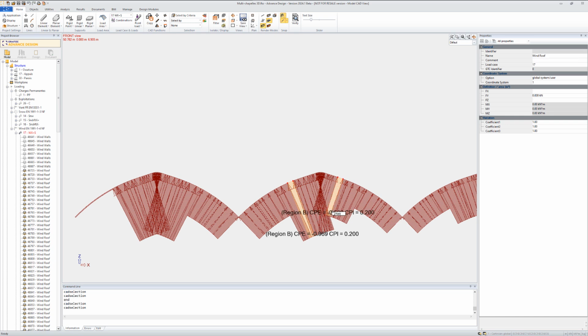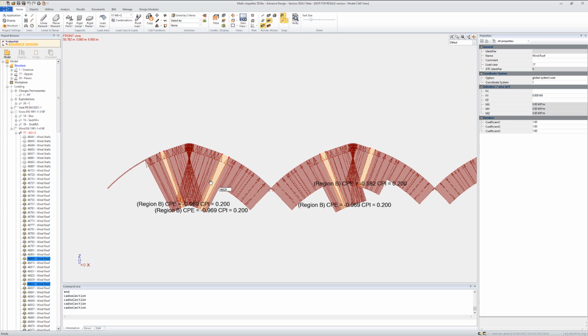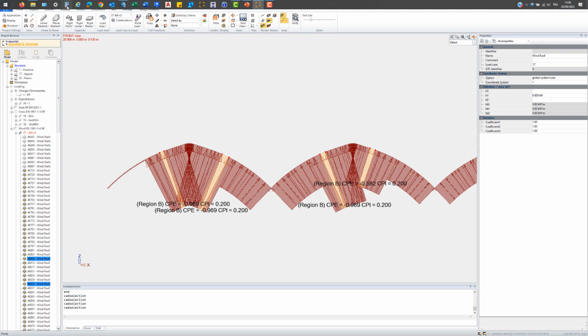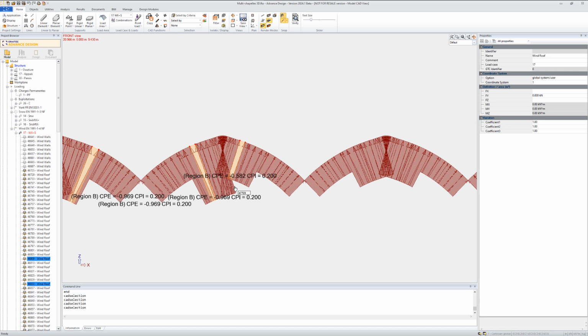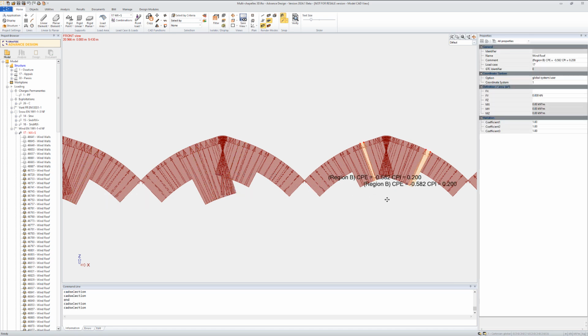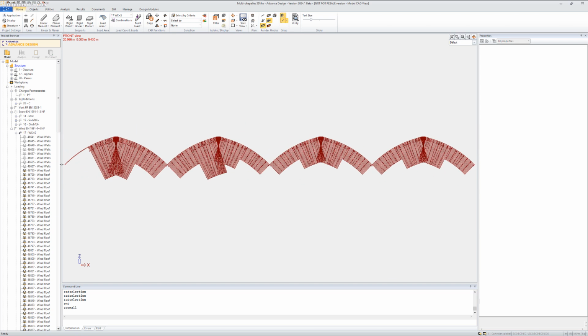and then you will get some B zone in the middle, but with a reduction, starting from the 1, 2, and after the third half roof. See, we have a reduction on the pressure coefficient. It's going from 0.9 to 0.5. And that is because we are applying a 60% reduction, and then you will have the same reduced value till the end of the building. So it's a mix of single vaulted roof and multi-span bays.